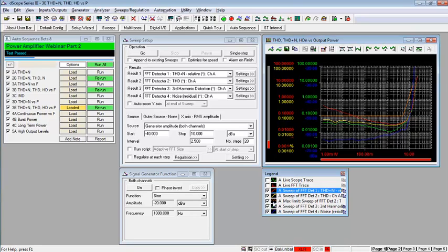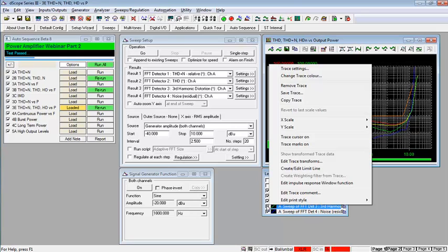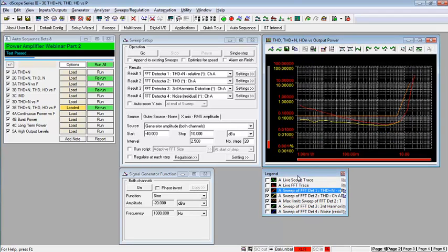However, if I look at my total harmonic distortion measurement, so this is THD only, no noise, in the yellow trace here, this is broadly flat at low amplitudes, and it's certainly below the limits that I've imposed on this test. So THD is not the problem. This amplifier, okay, there's a modest rise in distortion at low amplitude, possibly due to the effect of crossover distortion becoming more significant at low amplitudes, but it's not the reason for the failure in the test.